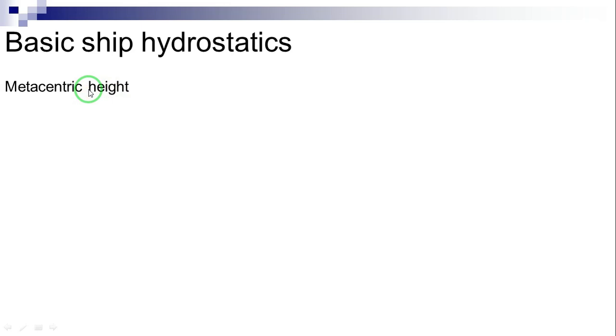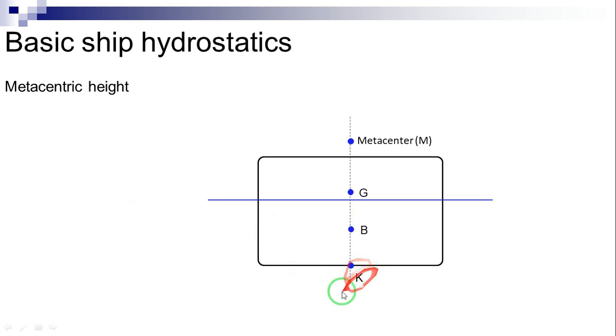Metacentric height. In the preceding section, we learned that a surface ship is initially stable if its initial metacenter is above the center of gravity. For actual calculations, we must find a convenient mathematical formulation. We choose a reference point K at the intersection of the center line and the ship baseline, and we measure vertical coordinates from it upwards.